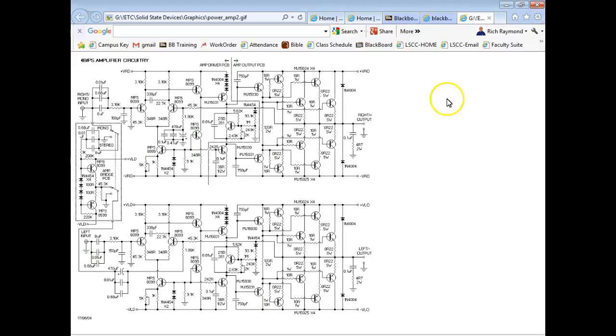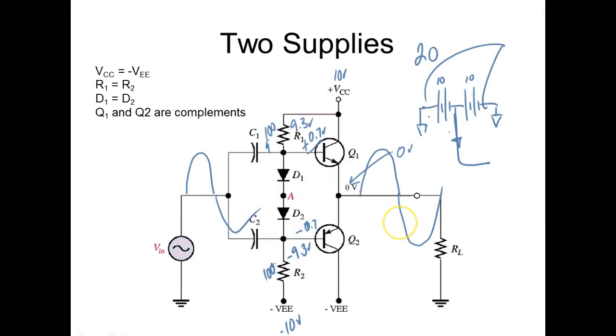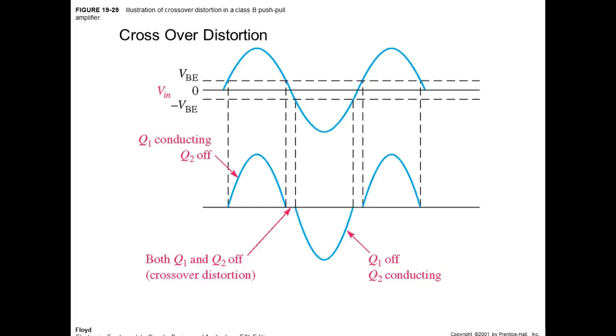So what we're going to do next is, I just wanted to show y'all, so what's the function of the two diodes? It's to take away the what? Prevent that what? Yeah, so what it does, it biases them until they're ready to be turned on, right? So what it does, it puts exactly 7/10 of a volt on that thing, but it still puts 0 volts on the emitter. Does that make sense?